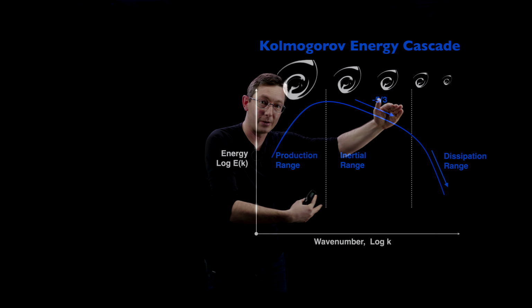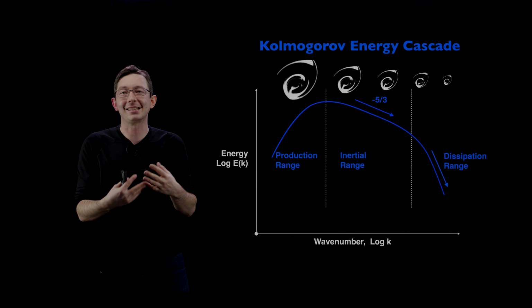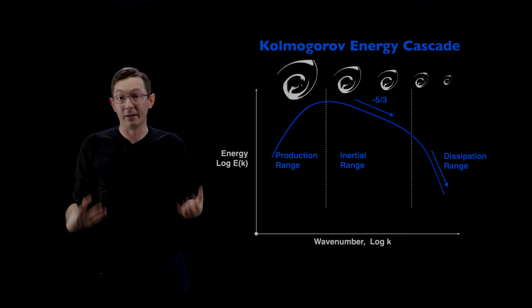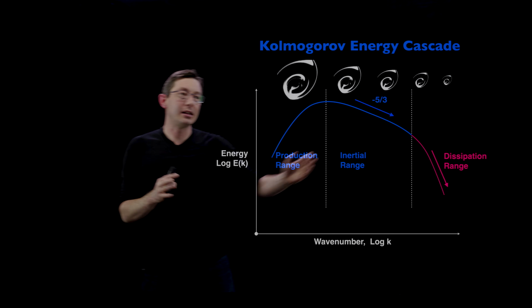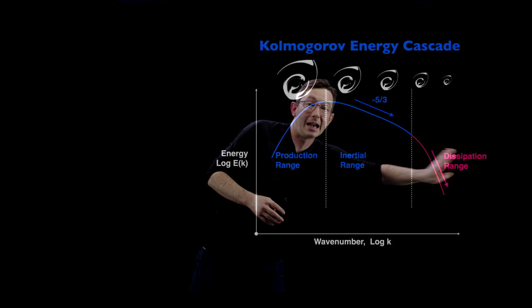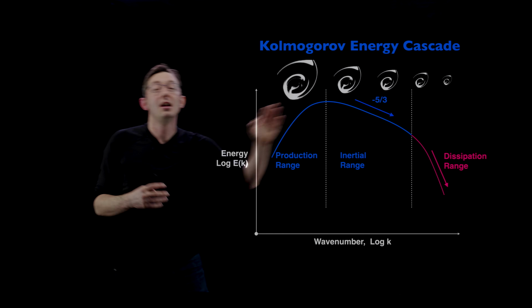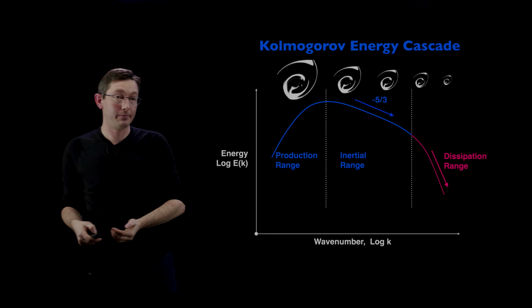This is the inertial range. And finally, you have a dissipation range where the turbulence acts effectively like a viscosity, or at least that's the model. And so the idea here is to basically just chop this off at some point, don't resolve these higher frequencies, these smaller structures, and just treat them as an effective viscosity, just like we did in the RANS equations.